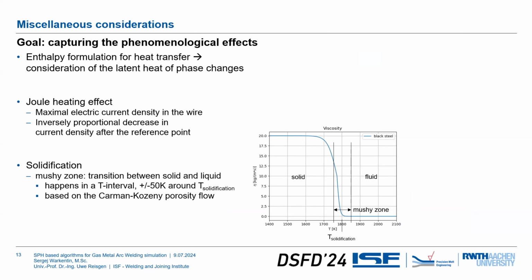But in the machine room, you just use Darcy. So in the Darcy flow, are you also using SPH or something else? Yes, it's the same, just fluid flow. So we use the impulse equation, and the impulse equation has a momentum sink that is considered by the Kozeny-Carman. The same equation is applied to the whole domain. Okay, thanks. Thank you.